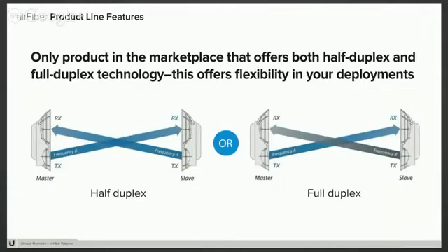As I mentioned, we support full duplex and half duplex as well. Here are a couple of typical configurations. Typically, in a half duplex setup, you would see that we'd be using the same frequency for receive and transmit. And typically, on a full duplex radio, you'd be using different frequencies. There's actually no requirement for that, as both modes can be supported whether you're in full duplex or half duplex, but this is typically what you see.